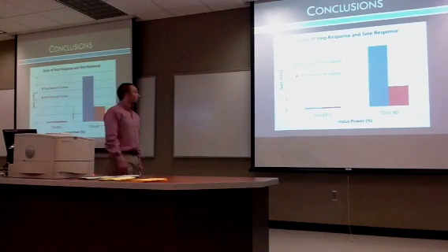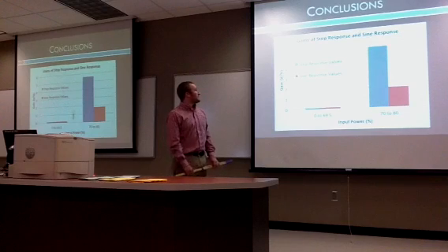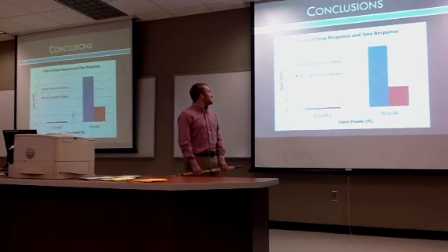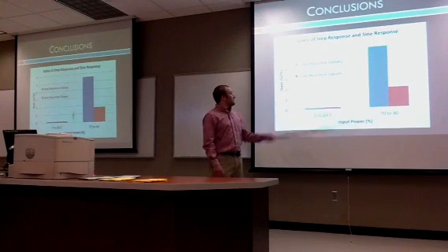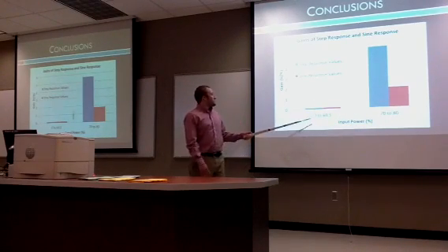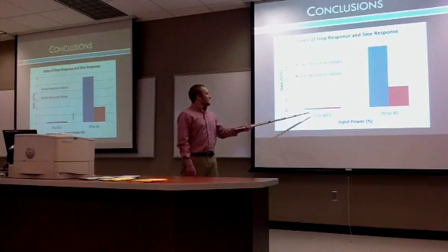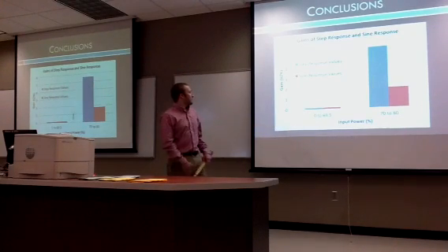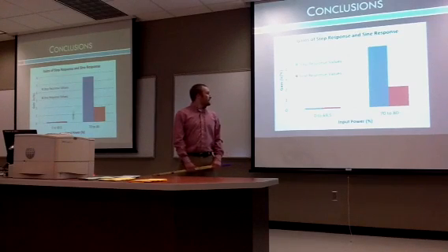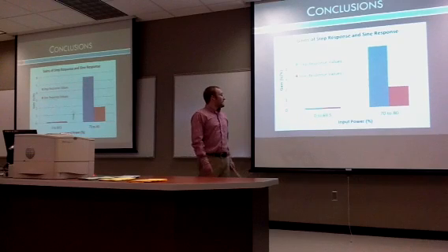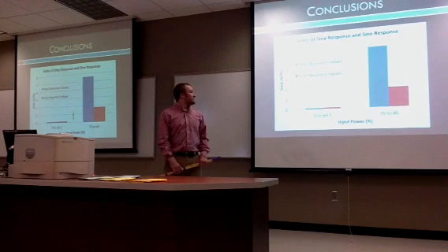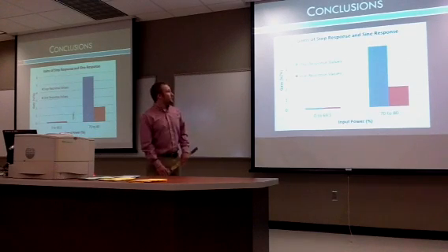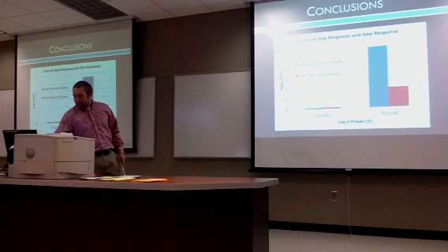And to conclude, I compared the step response and the sine response parameters. This is our gain. In the blue is the step response values, and in the red is the sine response values. As you can see, for 0 to 69.5%, the step response and the sine response were very close for the gain. They were at about 0.15 volts per percent. But for the 70 to 80% input power, it was a pretty dramatic difference. It went from about 5.6 volts per percent to about 1.8 volts per percent for the sine.